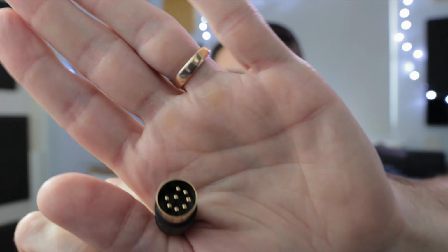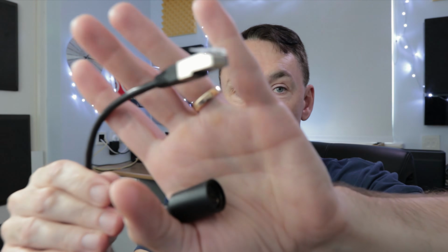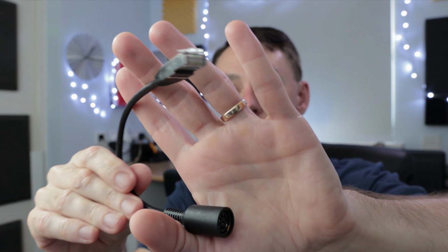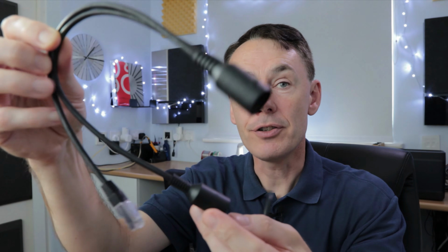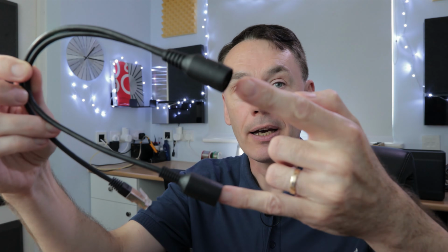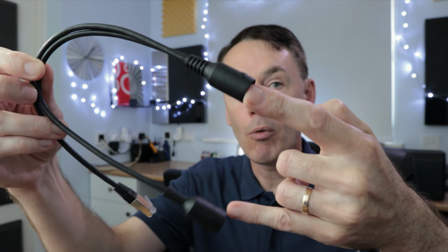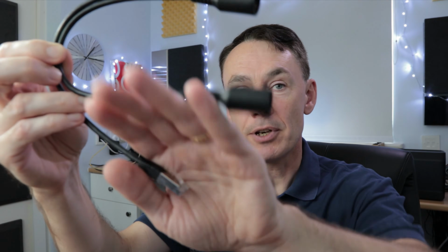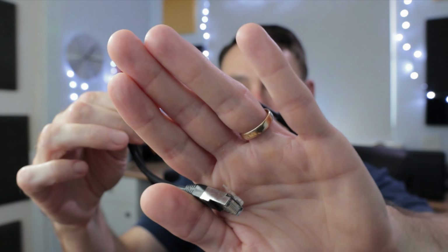If your TV is 2012 or older, then it will have the previous 8 pinned Powerlink connectors. And in that case, it's nice and easy to get everything working via a Powerlink to RJ45 adapter, which again, I'll link to everything in the video description. And I have both single and twin versions of these. So for example, if you have Beolab 8000 speakers, where each speaker connects separately into the TV, one cable will go to each socket on the adapter and they'll share the same RJ45 input and work correctly in stereo in the theatre.